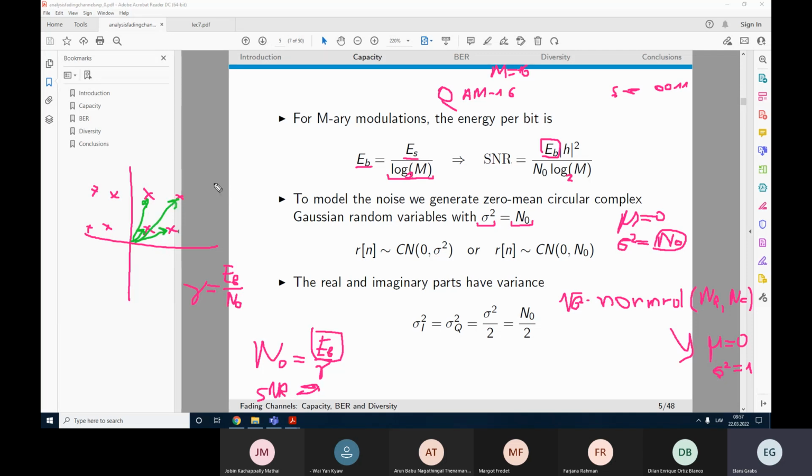Then we calculate the average energy of the symbol, and we divide it by 4 to get the energy of bit. Then we know what noise power density we need for this signal to noise ratio, and accordingly we know the variance as well, which is sigma squared, which we then multiply by this normally distributed signal. And that's basically how this function works.